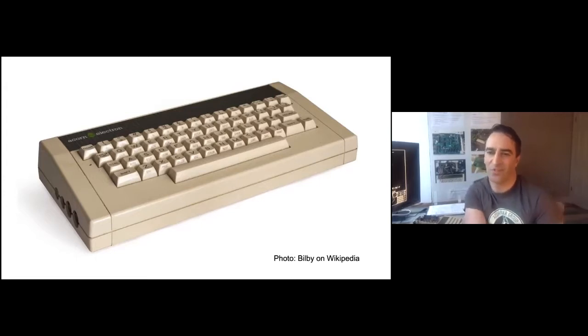Biggest limitation, it has 4-bit memory. The 6502 still sees an 8-bit bus, but there are only four 1-bit wide DRAM chips, and so every memory access takes 2 DRAM transactions. This means it has, at best, half the memory bandwidth of the BBC Micro. At worst, way worse. In some video modes, the 6502 is only actually running during blanking periods. It's got simpler video. There's some scrolling limitations.